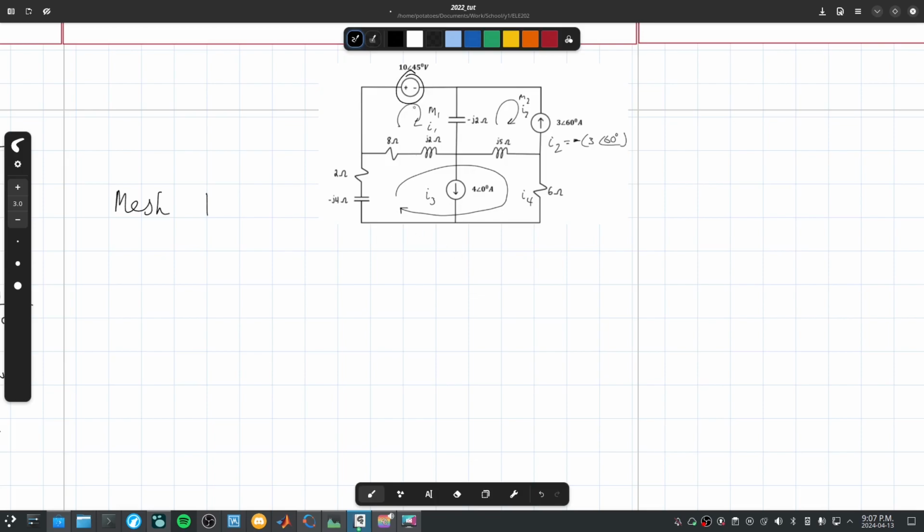So let's start. You're coming out the negative end of the voltage source. So that's negative 10, put in brackets, 10 with a phasor of 45. When you come out the negative end of a voltage source, you know that you're working in non-passive mode. So all of your loads need to add, not subtract. So, comes out negative end, comes to a capacitor.